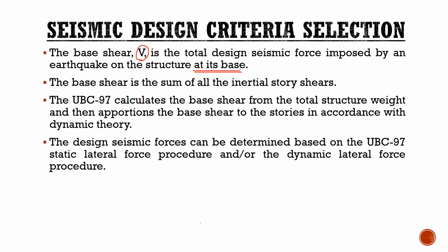Okay, so we call it base shear, since the force given by an earthquake is lateral, which is shear with respect to the members. The base shear is the sum of all the inertial story shears. So the UBC 97 calculates the base shear from the total structure weight and then apportions the base shear to the stories in accordance with dynamic theory.